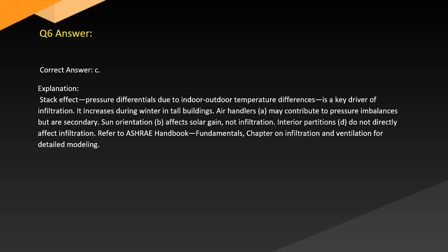Answer. Correct answer C. Explanation. Stack effect. Pressure differentials due to indoor-outdoor temperature differences is a key driver of infiltration. It increases during winter in tall buildings. Air handlers (A) may contribute to pressure imbalances but are secondary. Sun orientation (B) affects solar gain, not infiltration. Interior partitions (D) do not directly affect infiltration. Refer to the ASHRAE Handbook, Fundamentals chapter on infiltration and ventilation for detailed modeling.